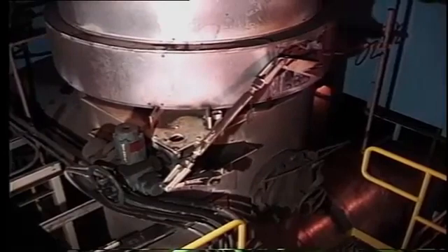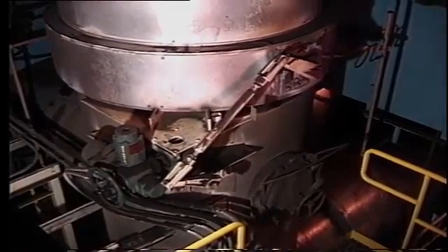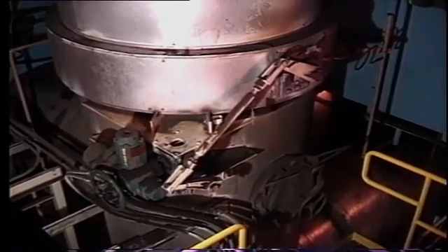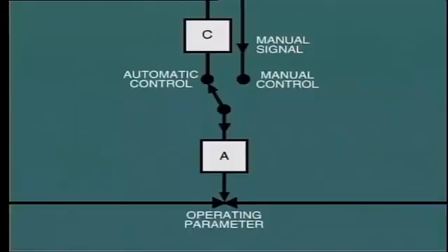The actuators generally are motivated by compressed air or precisely controlled electric motors and positioners. Even when we're operating the system manually, the actuators are still required to adjust equipment position. In fact, the changeover from automatic to manual control merely allows the operator to provide the driving signal to the actuator and thus enables remote operation. So let's take a look at some typical control circuits. Here we'll simply be looking at the logic of the circuit. The actual control system may be pneumatic, electrical, or digital, but the logic of the operation is the same.